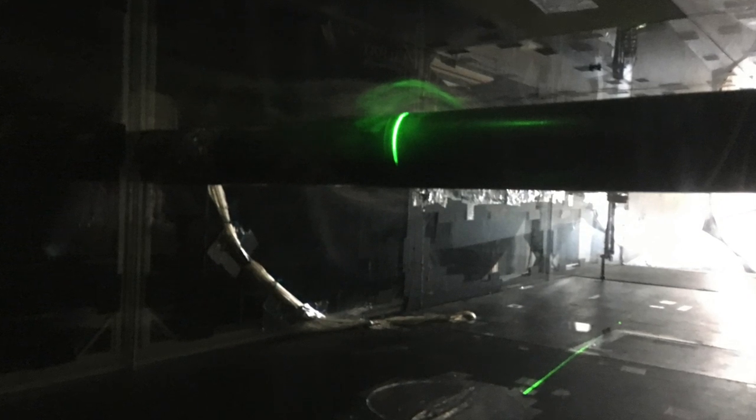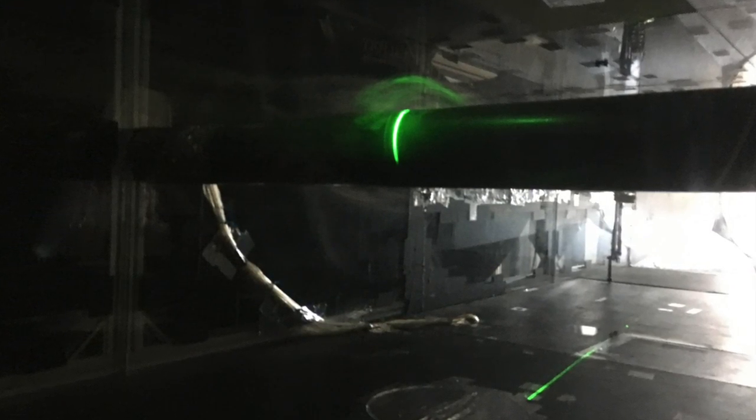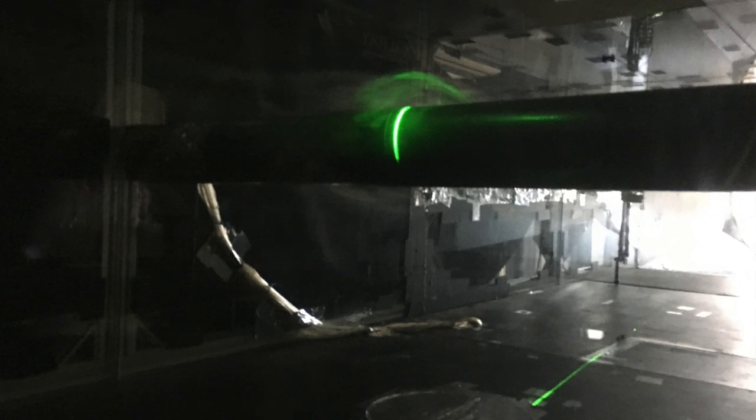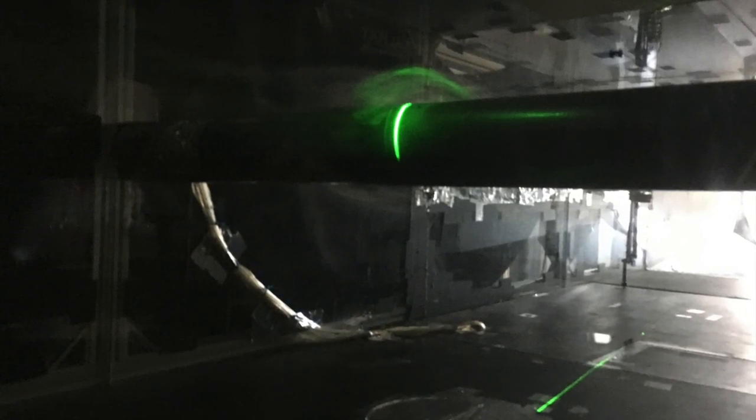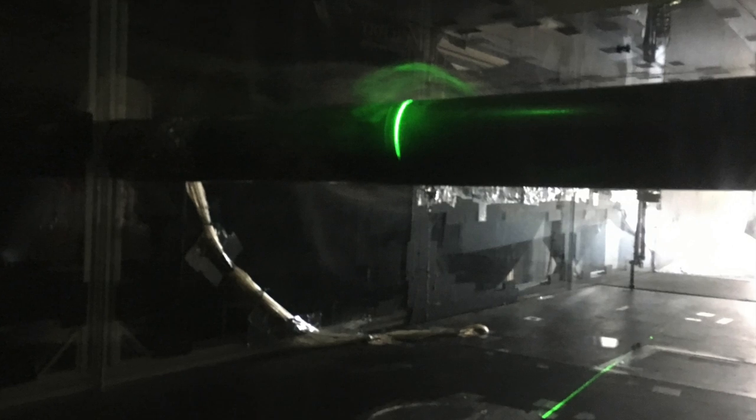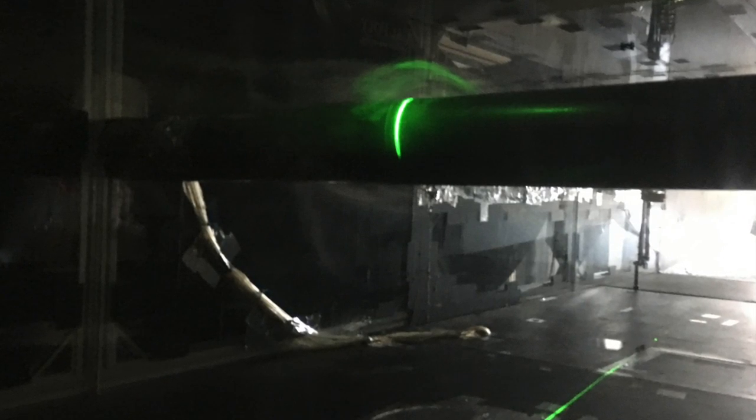When the light is perpendicular to the cylinder, it illuminates the flow of smoke over the cylinder, allowing for easy visualization of where the flow separates. With the light parallel to the cylinder, it allows us to view the smoke before contact with the cylinder, assuring us that the flow in the wind tunnel was turbulent even before interacting with the cylinder.